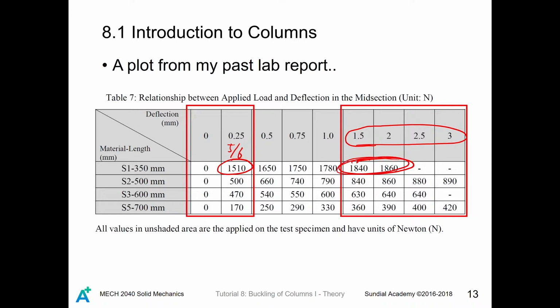Even when the applied load is arriving at 5/6 of the critical load, the deflection was still very small. But once you apply a little bit more load, then the deflection will increase very rapidly.